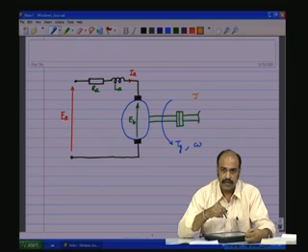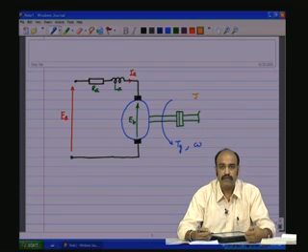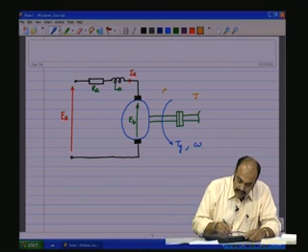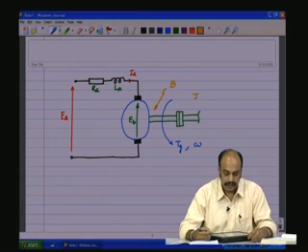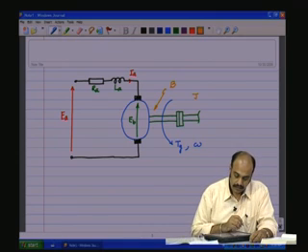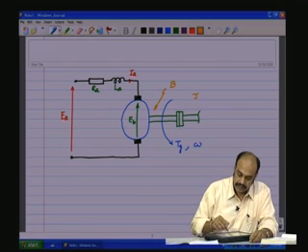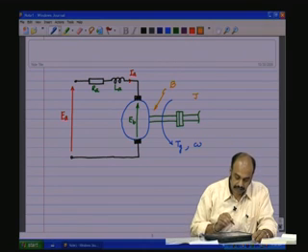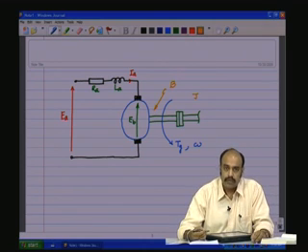and therefore, the state variable in the case of the mechanical domain which is involved with the parameter J would be omega, the speed. There could also be friction associated at the bearings, and we will call it friction B. Now, this is the electrical domain, and on the right side we have the mechanical domain. The link between the electrical and the mechanical domain is the motor.